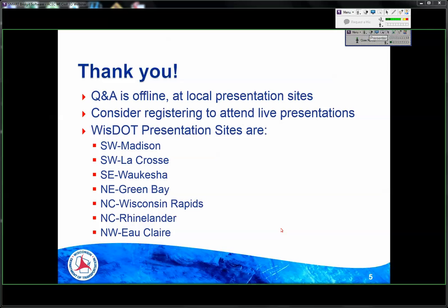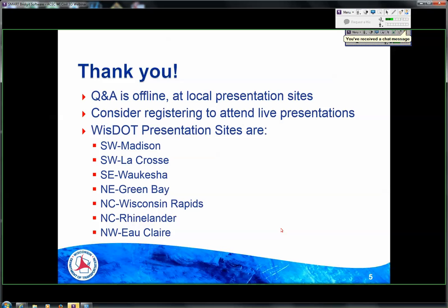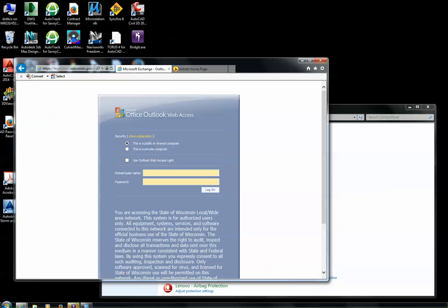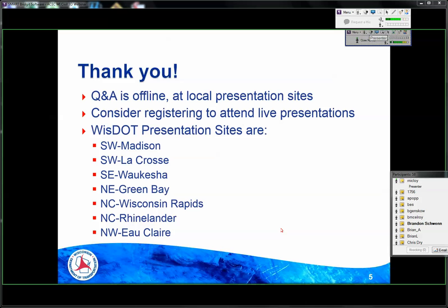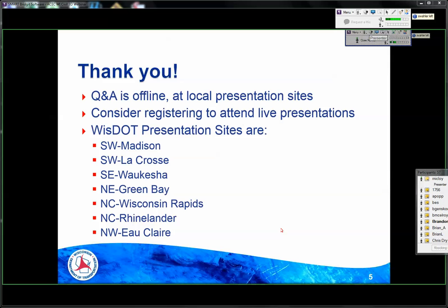I would also say, troubleshooting-wise, if you get into trouble, check the subassemblies for things like vertical surface links. Check for targets that are turned off or settings that are turned off, or maybe two settings conflicting against each other, like the measurements that you saw me do earlier, especially if you get the red slash issue. Those are things that you want to watch. And like I said, the help file can help during that process in a huge way.